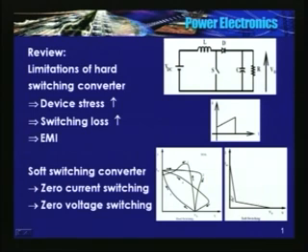So this area is nothing but the losses, whereas in a hard switch converter, see the locus. Current increases, reaches a fairly high value, voltage has not reduced and then comes down. And this is all because of the parasitic elements, and this is while turning it off.